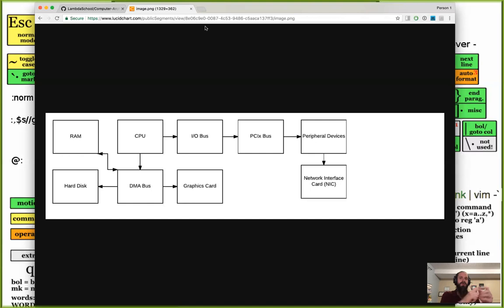And each pixel, and this is very specific, it depends on exact configurations. In the generic case, each pixel has 1 byte for the red channel it needs to display, and 1 byte for the green channel, and 1 byte for the blue channel, and then 1 byte for something called alpha. So it's 32 bits. Remember, a byte is 8 bits, and a bit is a wire, right? It's a 1 or a 0. A byte is 8 ones or zeros. And then 32 bits is 4 bytes times 8 million pixels. Gosh, what's 32 times 8 million? Let's just call it 256 million.